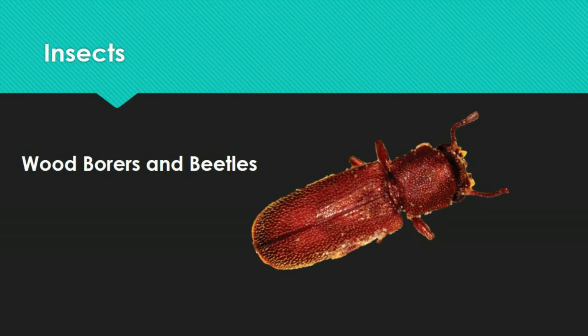Golden buprestid or soil beetle larvae may be found in older poles, and both of these bark bugs infest damaged trees or logs that haven't been peeled. Once the bark has been removed from a log, they will not penetrate it, and the presence of these beetles is sometimes overlooked until they grow and begin to depart the poles as mature beetles. Other insects frequently use these exit pores as entry points into a pole, and internal damage might be indicated by these poles. The chewing of these beetles and the holes along these poles attract woodpeckers as well, which we will discuss later.